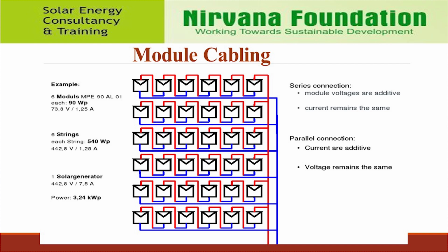The DC cables between the modules as well as between the generator connection box and solar power inverter are 2-core cables, usually a live red wire and a negative blue wire, both typically surrounded by an insulation layer.